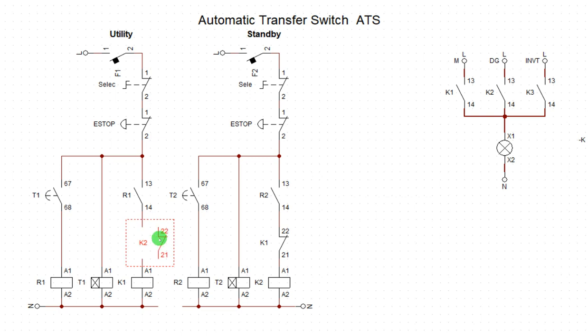Interlock K2 here. Remember that this is K1. This K1, before you energize K1, you go to K2 and come out. And that is why we have K2 here. Now this K2, before you energize it, you go to K1 and before coming back. That is why I have K1 here. I think that is clear.